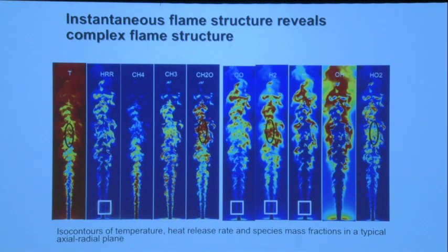The other thing to note is that we see a lot of intermediate species accumulate or be produced downstream in the jet at about 20 to 30 diameters. We see formaldehyde there, and we see lots of H2 and also HO2, which starts to develop as the temperatures go up. They're either developed or they got transported, because HO2 is kind of long-lived, as is formaldehyde. So it's quite interesting that there's very little heat release upstream, and that it's burning much more robustly as you move downstream.